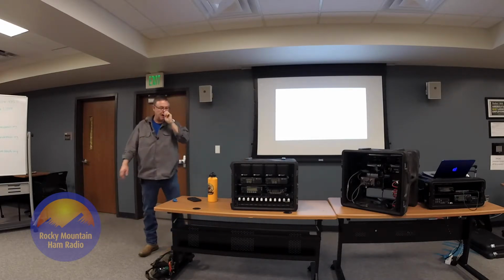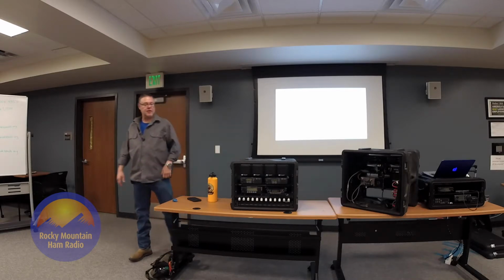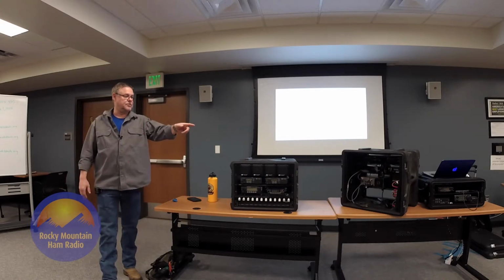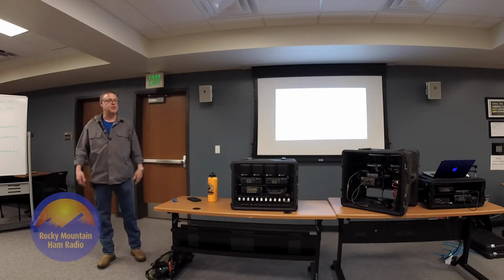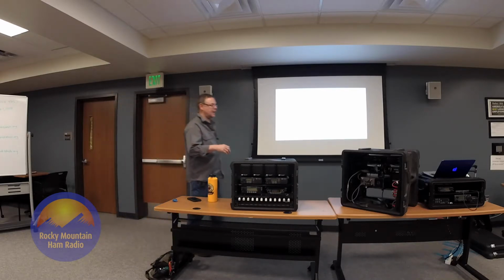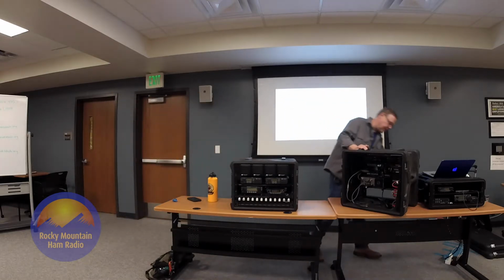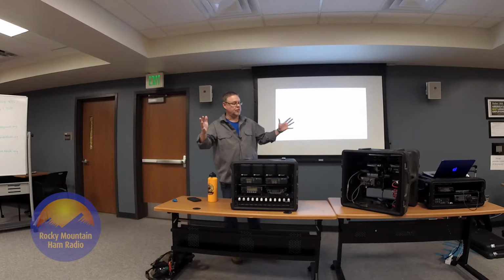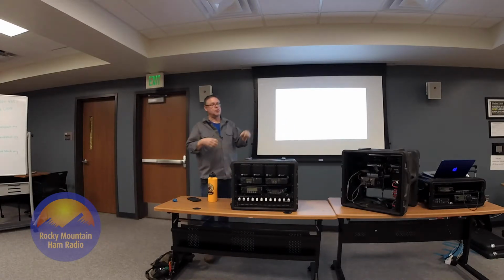It doesn't work. These boxes get warm inside, either from the sun pounding down on them or the equipment operating. Like John says, they delaminate, it comes off, and all of a sudden you're picking it up and things are banging around inside. Take the time. Power supplies, they don't come with mounting brackets. It doesn't take much to go down to Home Depot and buy one of their 3-foot strips of metal and bend it and build your own mounting bracket.